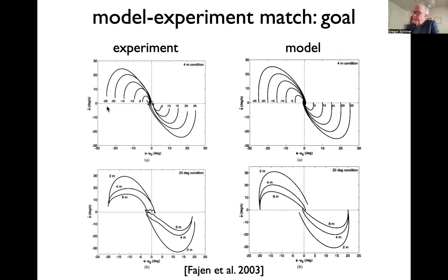You see that when the target suddenly appears out of nowhere, there's this initial transient that is not consistent with the equation that we had. We would say at any of these headings, we should have the same initial turning rate, and that required this second order turn to be headed in some kind of, it takes a little amount of time to get onto the correct dynamic curve, and you analyzed that in the exercise. This is the same plot for different initial distances from the target, and you see that the second order model just gets that just right.